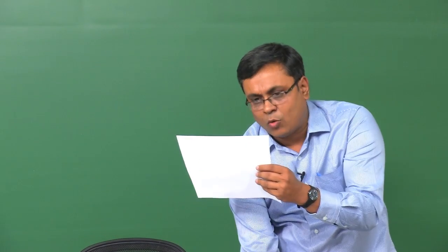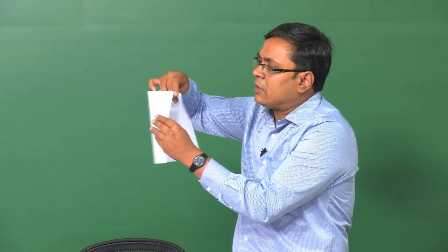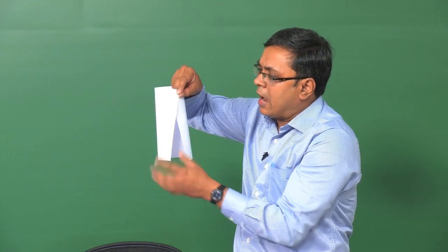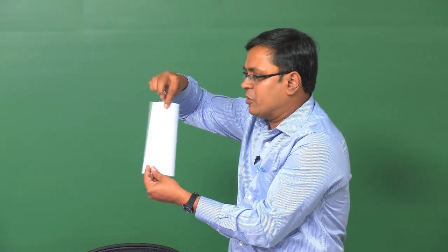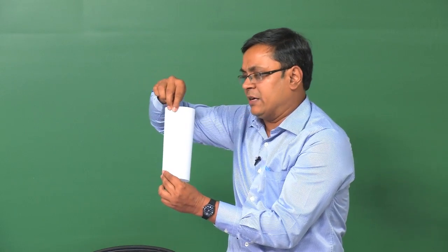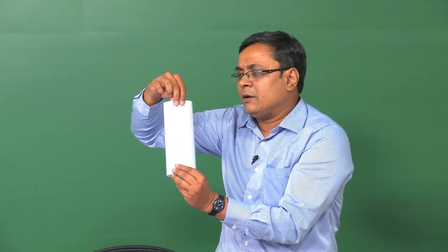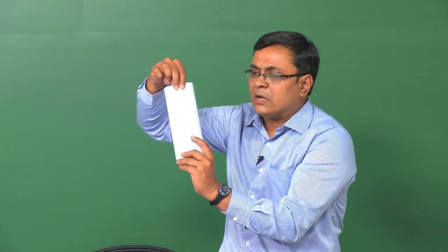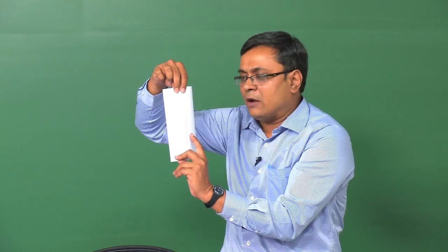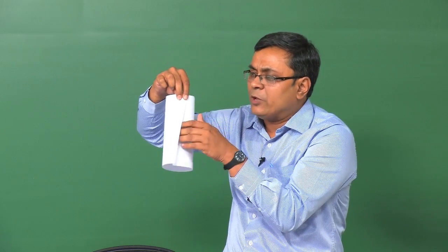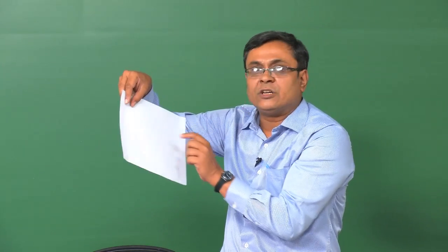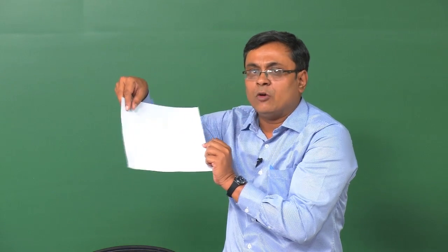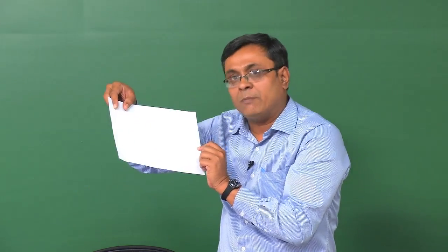I take a coaxial cylindrical surface and wrap it around the turbo machine, around the impeller blade, let us say, and then these blades will pierce through this paper and we will get holes. Now, if we stretch out the paper, we will get the positions marked on this paper, which are the marked positions for the blades.